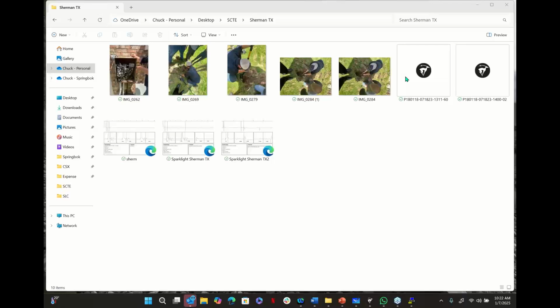Typically, you'll have a pulse width button, but depending on which TDR you're using, there's also going to be some sort of automatic range feature. So if you start off at 50 feet, most TDRs will automatically start off in the smallest pulse width available. But then as you bring on more cable, let's say you get to 100 feet and then 200 feet, it may change from possibly a 1 nanosecond pulse width to maybe a 25 nanosecond pulse width.